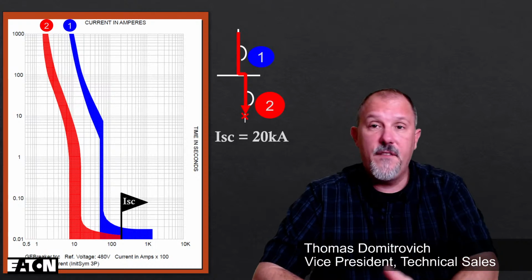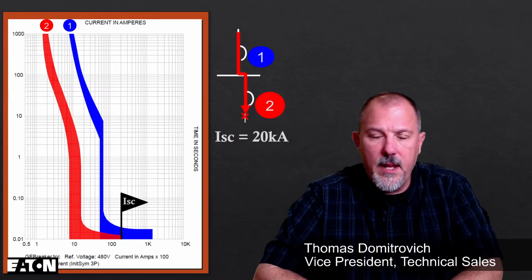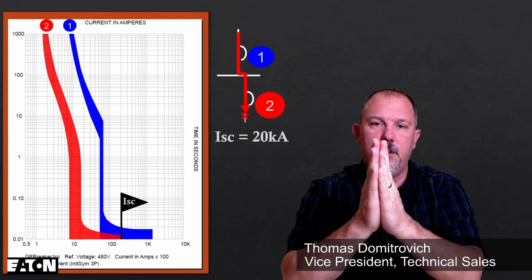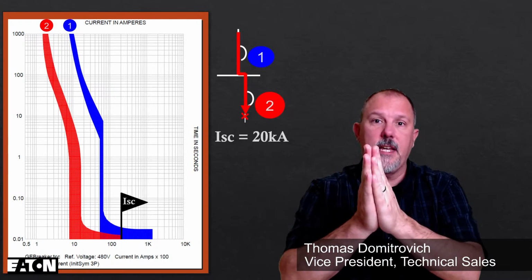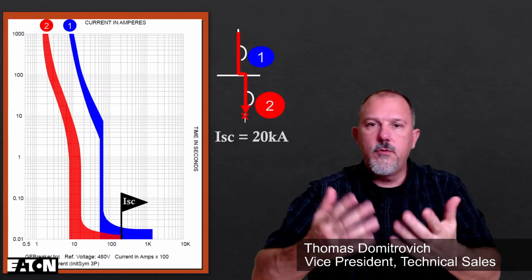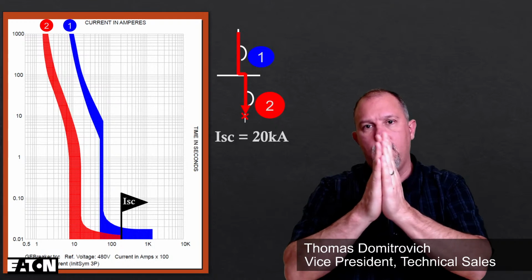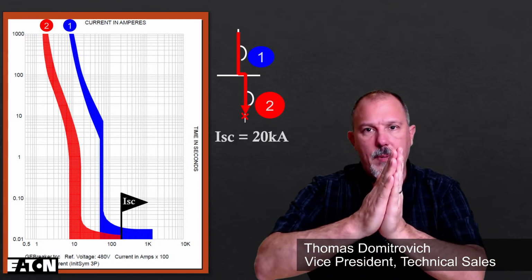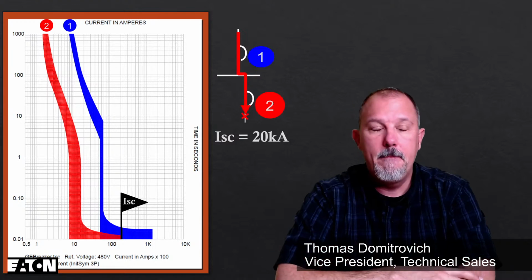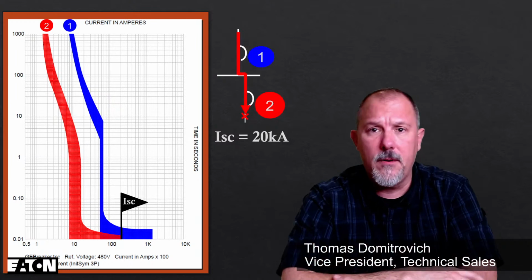I have a video on my YouTube site that shows you a 20 amp, I think it's a 20 amp thermomagnetic circuit breaker. I call it the clapper. There's a plunger in there that you're sucking in. There's no bimetal. There's no deformation. You're not trying to bend a bimetal and estimate where did it begin and is it already hot? Is it already somewhat bent? Because on a short circuit event, you don't care about that bimetal.